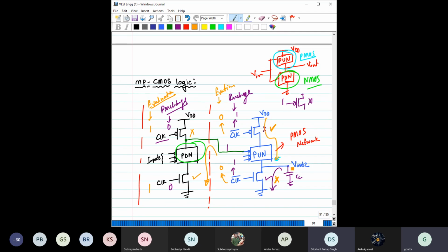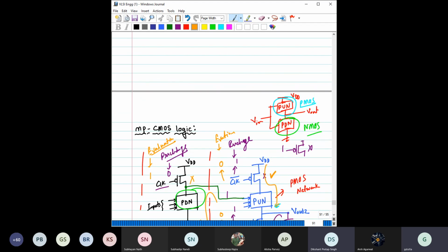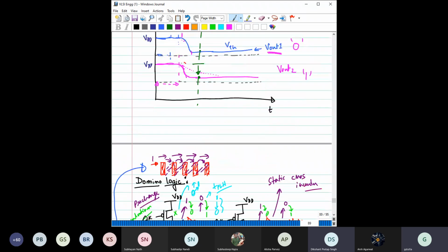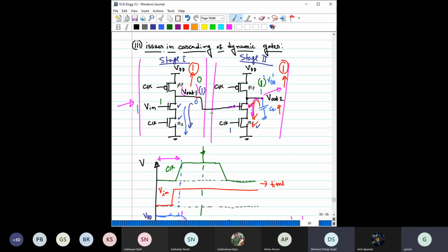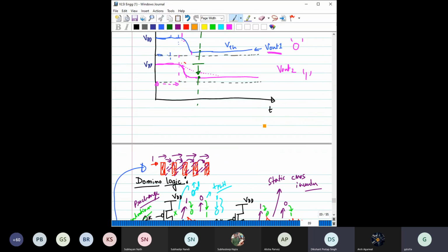So basically the issue, I think you are able to understand, right? The issue was happening because all the MOSFETs in normal dynamic logic gates were NMOS, unlike domino logic. So during pre-charge, the next stage would also turn on the next transistor. Obviously if it is not an NMOS and has a PMOS, that could have solved it.